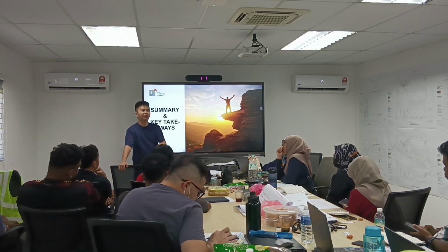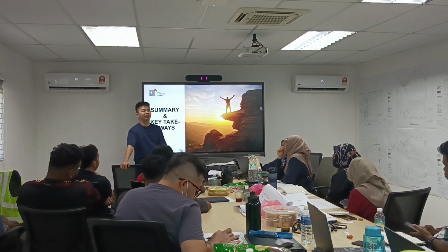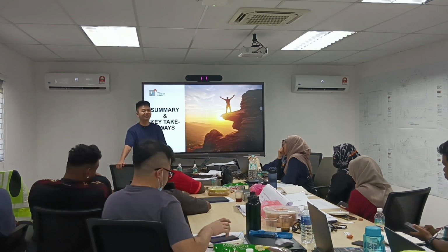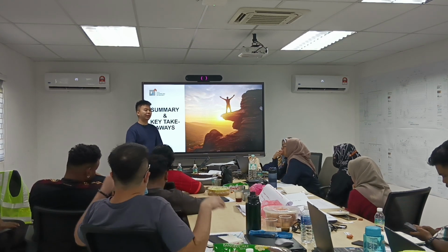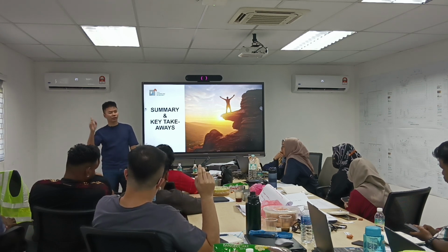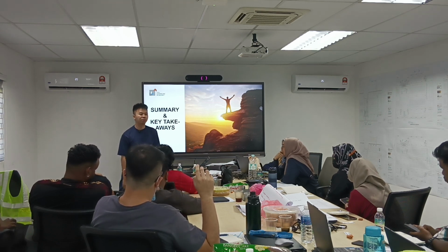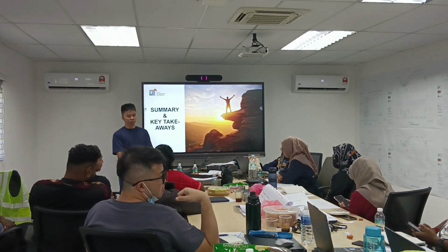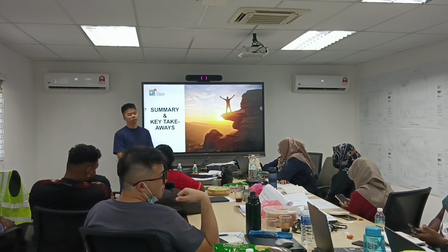You allow construct and do drawing. This is a wrong philosophy. We do drawing and construct. If we construct and do drawing, then you ask the designer in the office to go home first. Yeah, that's why I don't like this. If I'm the one handling them, I will ask the contractor to redo. I don't care. As it is a 10 to 50 mm difference from the actual shop drawing to the outside, we have no issue with that.